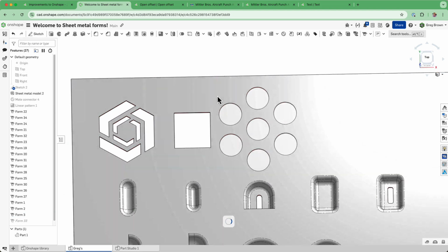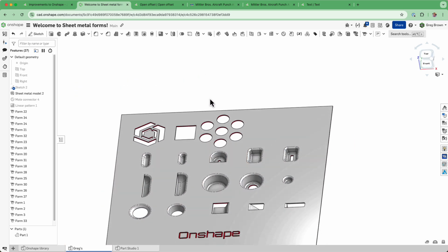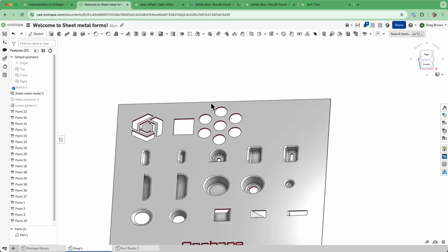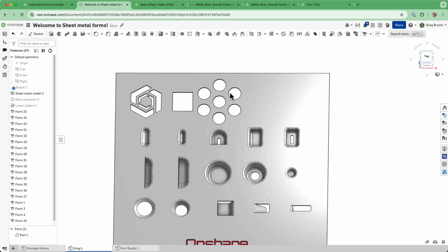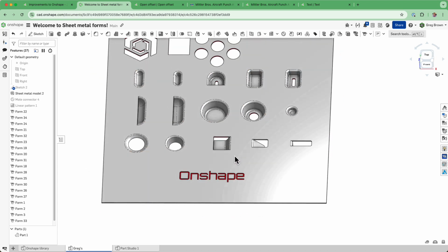If you want to do that, the only thing that you have to do, which is kind of special, and not hard, is you need to make a single body out of the punch. If you have these 7 different bodies when you first create this punch, you're going to have to create one body which connects them all together, and it's kind of trivial, but you do need to do that. You can only have a single removal body.